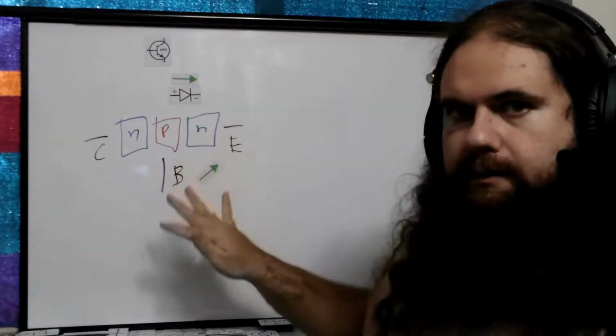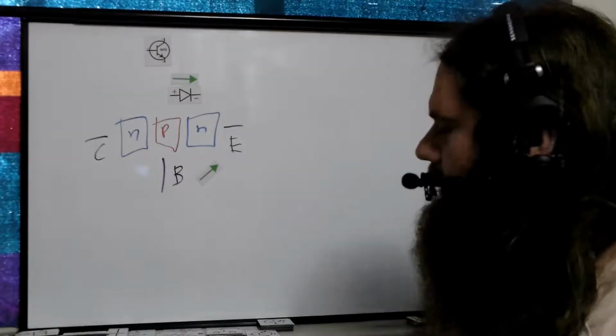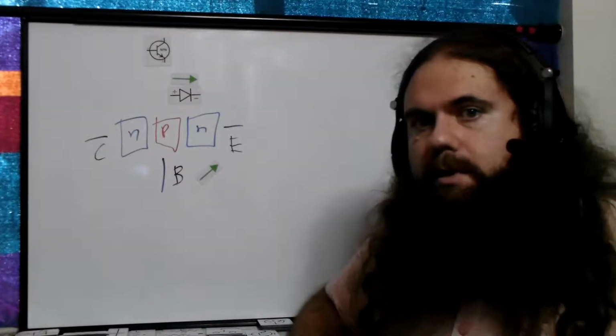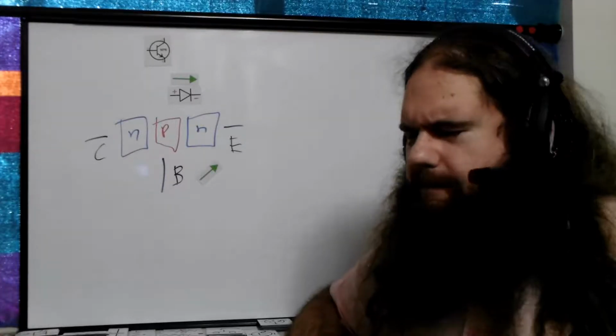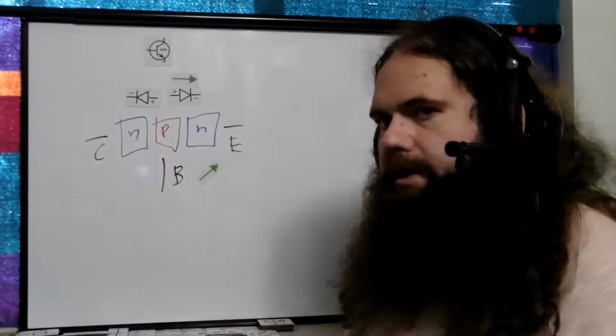If we do not forward bias that junction, the transistor is off. So that's step one. Now, if it's on, because if it's off, it's just off, it has two modes, active and saturation. That is the other junction. This junction, which is once again, effectively a diode.